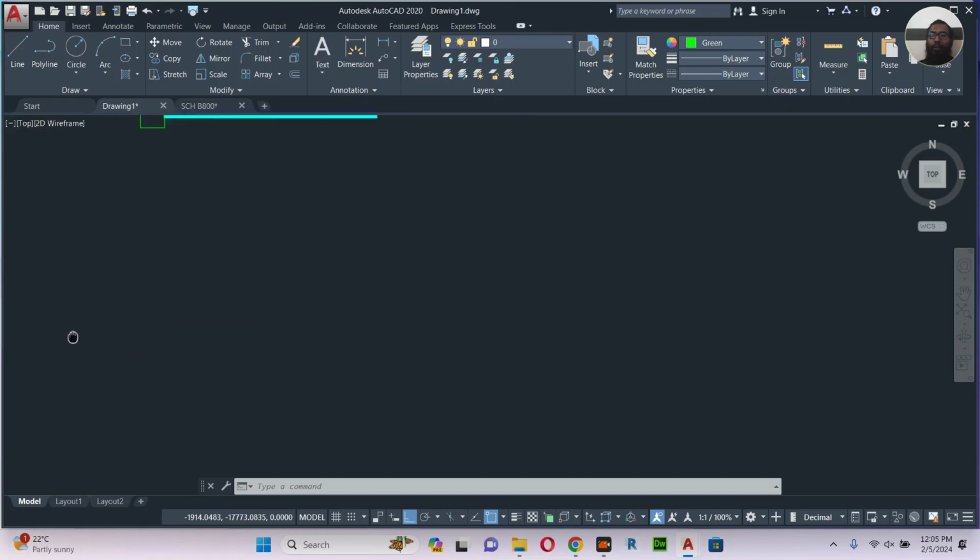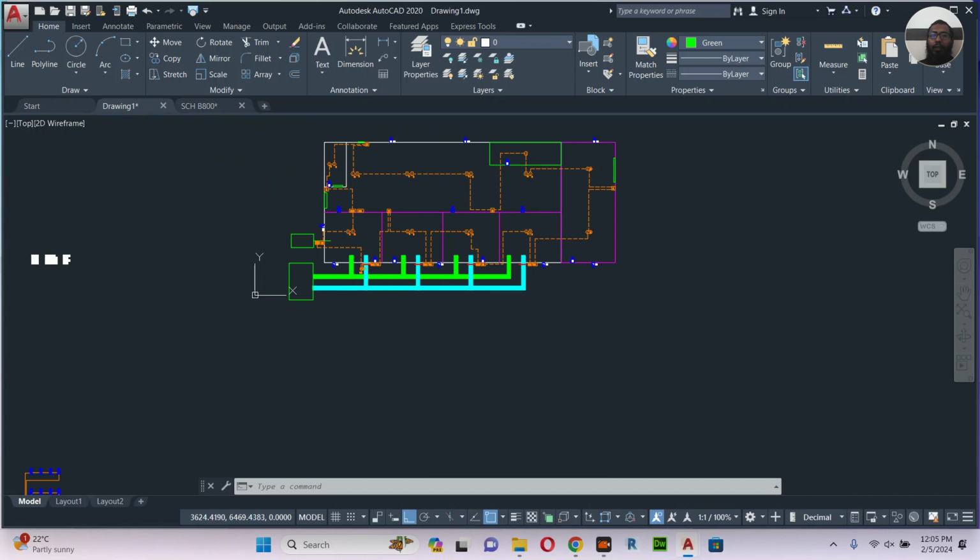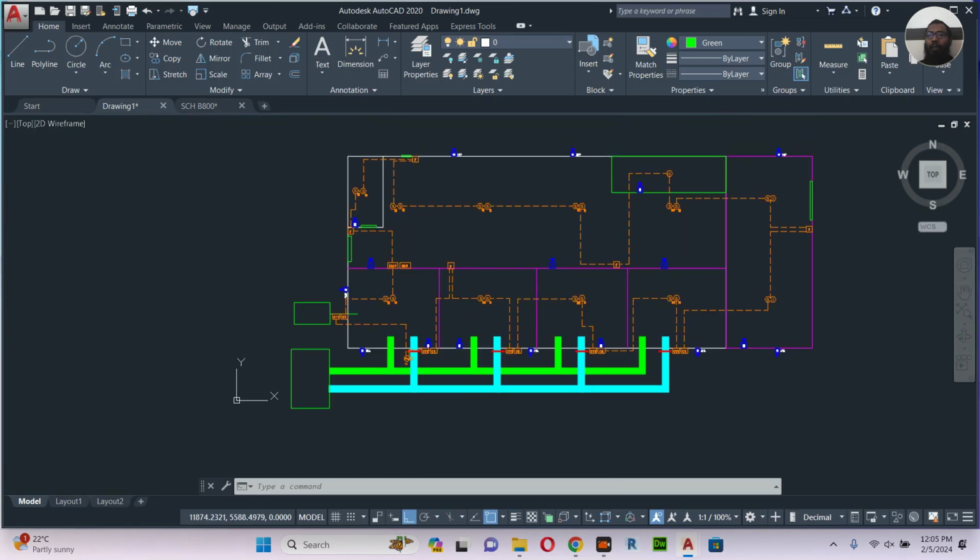example. So let's go to the drawing. So let's say this is bedroom 1. So there will be the same plan in the mimic panel. So this one has a certain number. So the programmer will make a program that if smoke detector 001 triggers or detects anything, this LED light should be switched on. So he makes the program like that, and that particular LED light he will put in this particular room area inside the mimic panel.